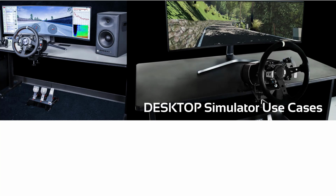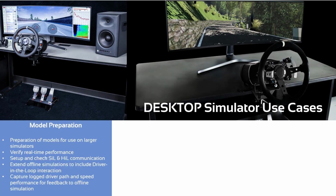There are a number of use cases for desktop simulators. First, as a platform for model preparation. This is for preparing models for use on larger simulators, for verifying real-time performance, and for setting up and checking SIL and HIL subsystem communication. It extends offline simulation to include driver-in-the-loop interaction, and it captures logged driver path and speed performance for feedback to offline simulation.